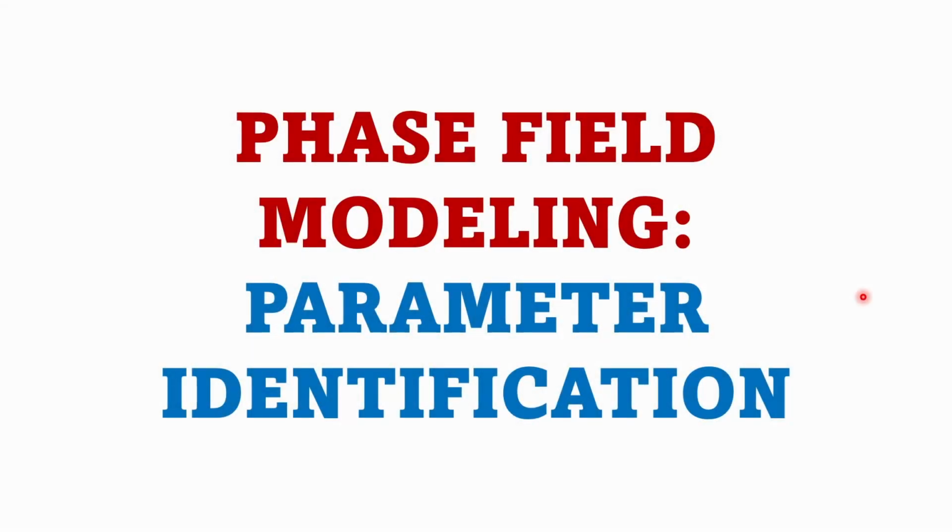So after quite a long time, and I would suggest going through the first two lectures of phase field modeling that I had talked about earlier. And today we'll start with phase field modeling parameter identification. So I'll be talking about how you decide on the different phase field parameters like the length scale parameter LC, and of course how it relates to the material critical energy release rate GC.